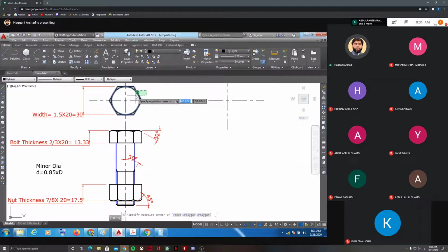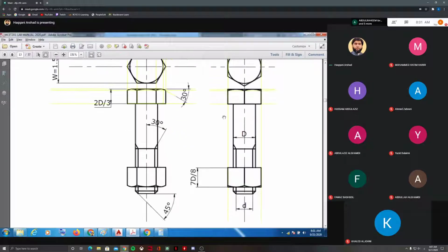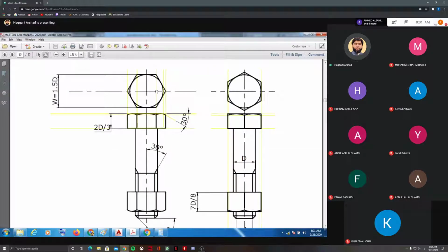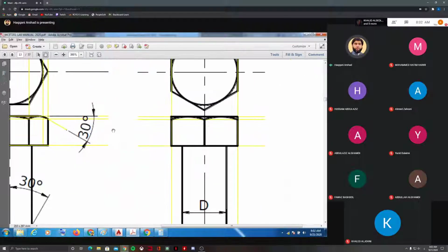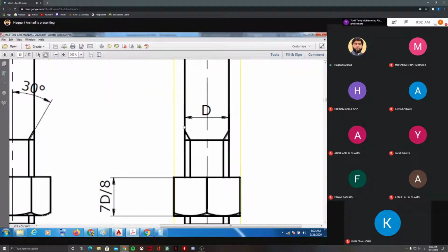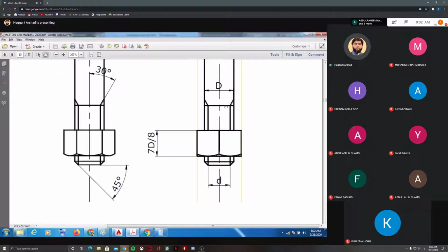What I'm going to do is, for this exercise, if you see the side view, simply this hexagon is slightly rotated 90 degrees. You see this is side view, and that's why you see there are only 2 arcs on the right. There are not 3 arcs because it's just a side view, and there is no angle here. If you zoom in on the side view, see there is just a box. There is no angle. Just you have arcs here for the bolt and nut, and the remaining, the capital D, small d, the angles will be same.